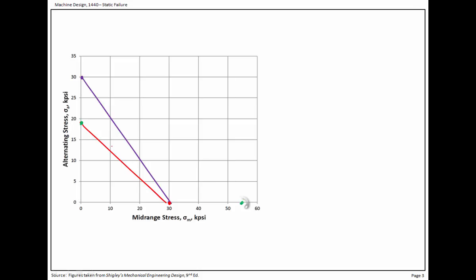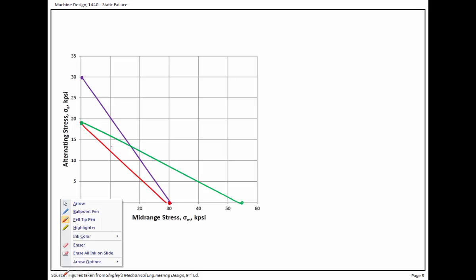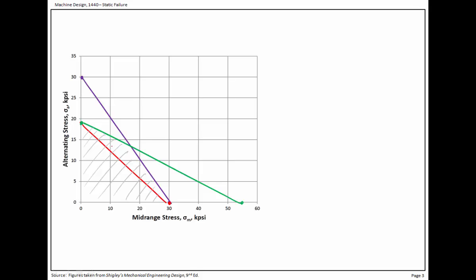So in terms of what the modified Goodman is, I'll go a very light gray, and I'd color in this portion right here, but the Langer sort of chops off the modified Goodman. Okay, so this is the Goodman up from this point to this point, but the Langer cuts it off. All right, so that's the first part of the problem.